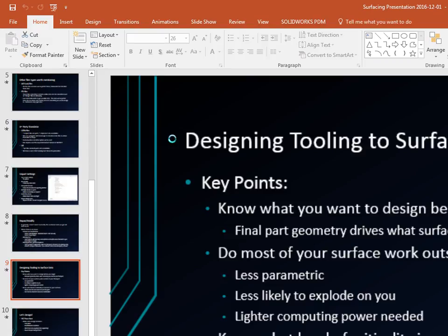All right, well, see, that's what I ran into, and that's what I asked. I have had replace face work for me. It's more for, on a simpler geometry, if I just have a boss coming up to one face, and I want to replace that with a face that's higher or lower or different geometry, and there's no fillets on it or anything, I can get it to replace sometimes.